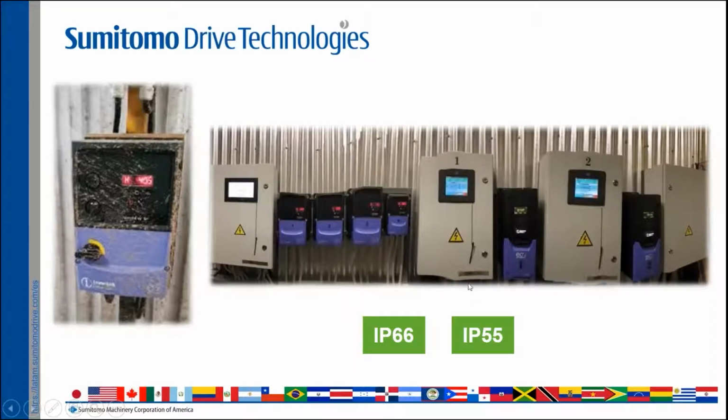And this leads me to another important factor for my drive, and this is the space available for the drives. This can be very helpful. For example, if my drive has IP66 or IP55 level of protection, I won't need an extra control cabinet for my drive.